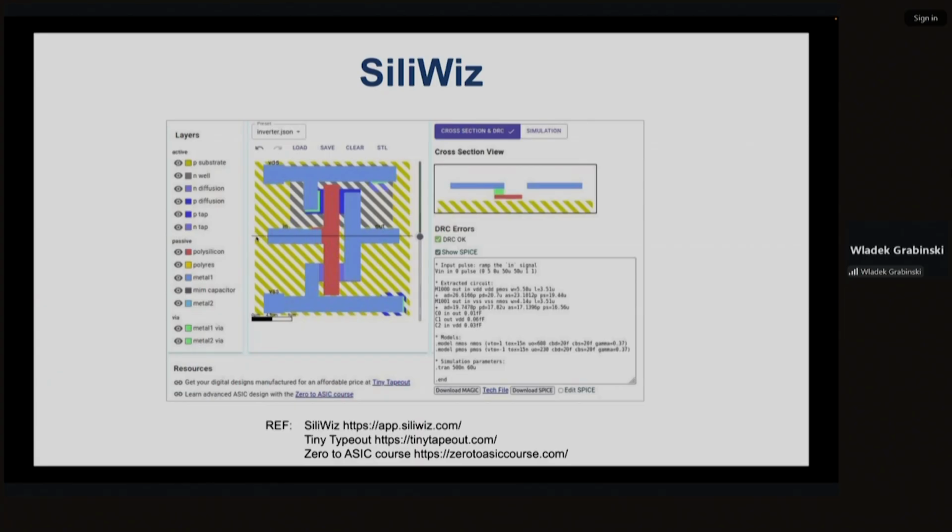You can move this hair cross line to see cross section, and I'm sure you are recognizing metallization input line with contacts touching poly in red, and then the output metallization here in this cross section on the inverter output.